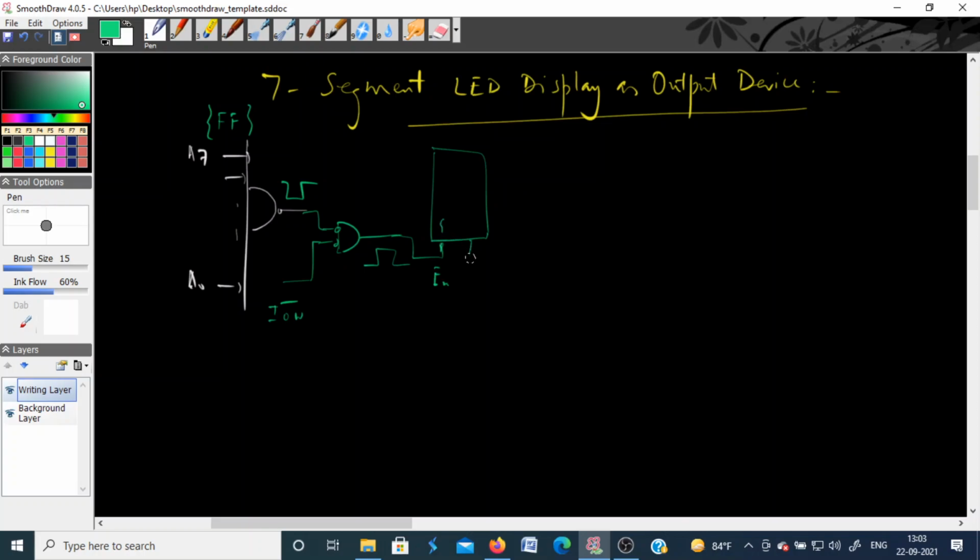So there was one pin which was an active low output control pin. Then you have plus 5 volt VCC, and a ground pin. Okay, and then we have 8 pins for input D0 to D7, and there are 8 outputs, Q0 to Q7. To the output of the latch we have connected LEDs using current limiting resistors. All the anodes of the LEDs are connected to plus 5 volt.